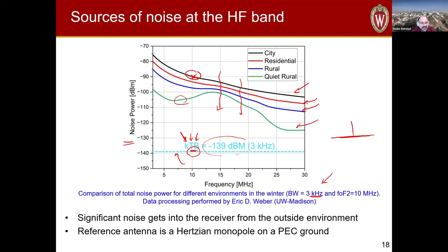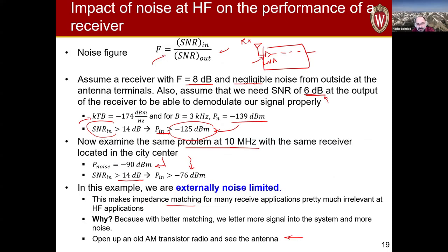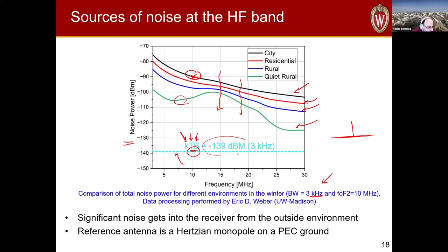So as the environment changes or as the technology changes, these numbers can change, and also depending on the type of antenna that you have, this can change. I think the purpose of curves like this, at least for what we do, is to understand that we're dealing with a really noisy environment. If you're doing some sort of link budget analysis, you have reasonable estimates on how much power you need to transmit and what sort of antennas you need, and there are going to be a few dB of variation up and down in your link budget analysis anyway. It's a little bit uncertain.